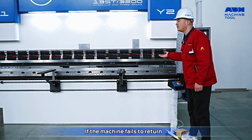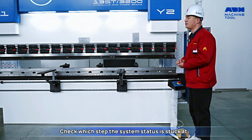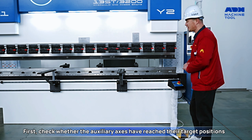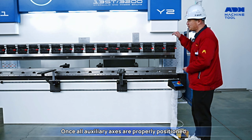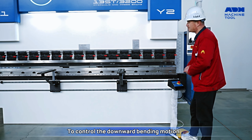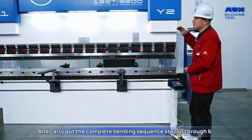If the machine fails to return, check which step the system status is stuck at. First, check whether the auxiliary axes have reached their target positions. Once all auxiliary axes are properly positioned, the press brake ram will then allow activation of the foot pedal to control the downward bending motion and carry out the complete bending sequence, steps 1 through 6.